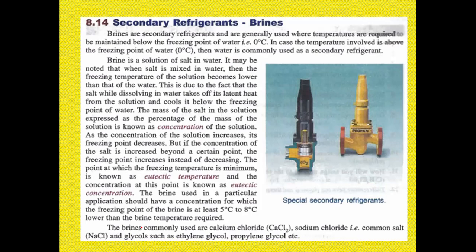Then what is a brine here? A brine is a solution of salt in water. It may be noted that when salt is mixed in water, the freezing temperature of the solution becomes lower than that of water. This is due to the fact that the salt which dissolves in water takes its latent heat from the solution and cools it below the freezing point.